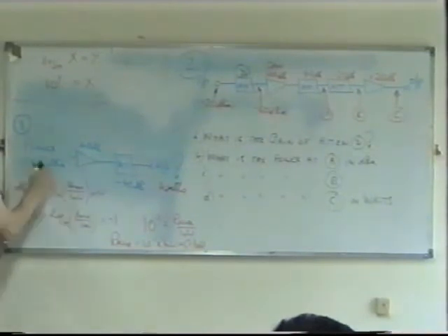No, dBm is a measure of power. There's no such thing as loss, it is an absolute measure of power. So what does the minus sign tell you? Can you get such a thing as negative power? Less than 1. Yes, that's exactly what it means. It means the power is less than 1 milliwatt. Remember, everything is referenced to 1 milliwatt.